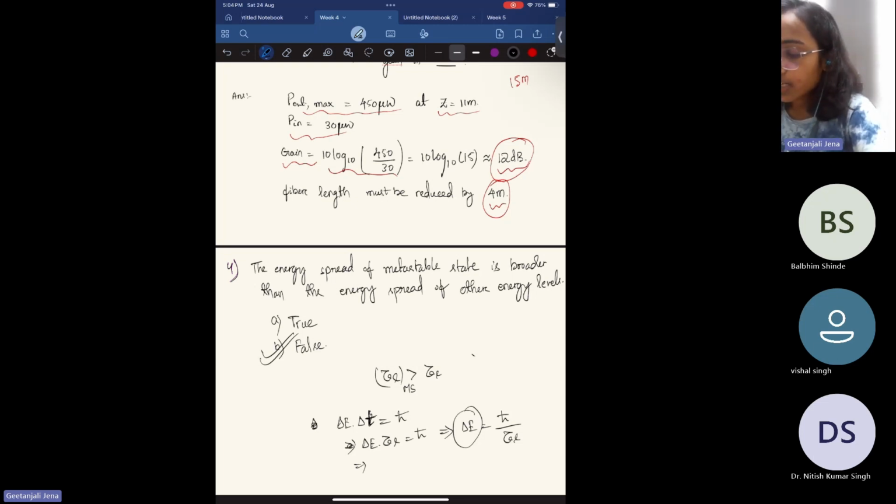Similarly, in an optical oscillator, we have a pump, which is 980 nanometer for the EDFA fiber, and an active medium. We see different kinds of active medium, Nd:YAG, EDFA, Nd glass, and we have an optical resonator, which typically consists of two mirrors. One has a reflectivity of 100% and the other has a reflectivity of 90%. Now we'll see what are the different types of optical resonator that we typically use in a system.